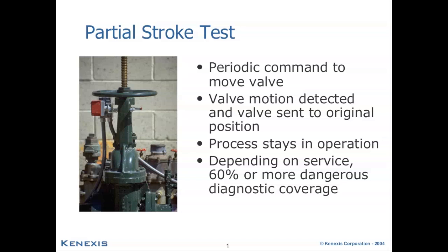The value of doing this type of test is that the process stays in operation the entire time that the test is occurring. So you're not going to upset your plant, you don't need to stop operations, and you don't need to have any elaborate bypassing mechanism that's going to allow you to run the test while the plant's in operation. And depending on what the service of the valve is, what type of valve, you can achieve a 60% or greater diagnostic coverage.